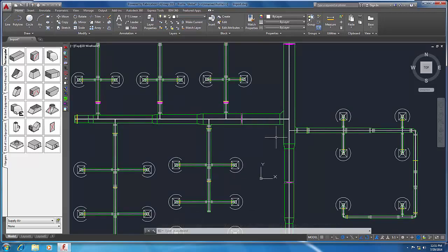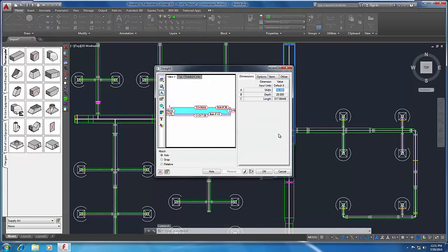Double-click on a straight duct. Avoid clicking on the design line. The Item Properties window appears for this item. This item was imported from Revit using the Store as Design Line element method. Notice that the seam type, connector type, and dimensions are set to the service specification assigned during the mapping process. Click Cancel to return to the drawing.